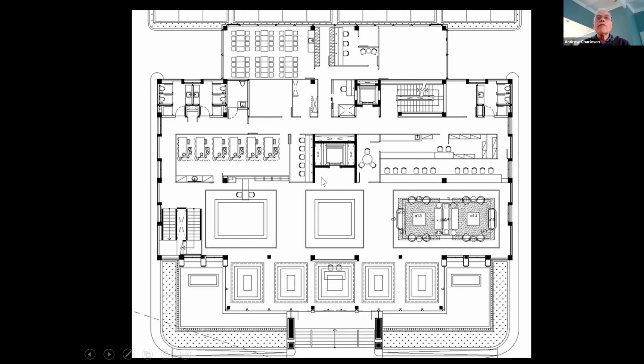Now, first of all, we've got these two possible shear walls. They could be designed to resist earthquake load in the Y direction, but they're quite short. And so I don't think they would have enough strength. And you've got tiny walls here that also would be too flimsy, too flexible to offer any resistance.